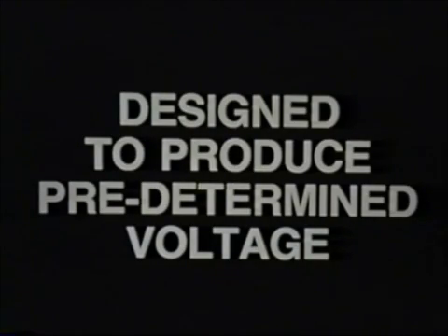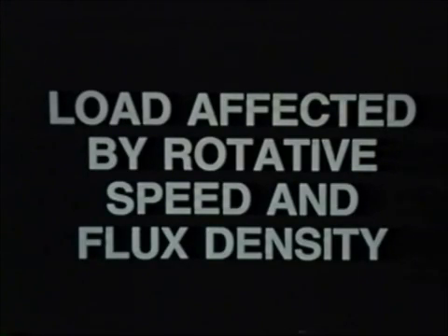Many factors affect the magnitude of the output voltage of an alternator, but they are designed to produce a specific, predetermined voltage. Varying the conditions of load, rotative speed, and flux density can and will directly affect the output voltage of the machine.